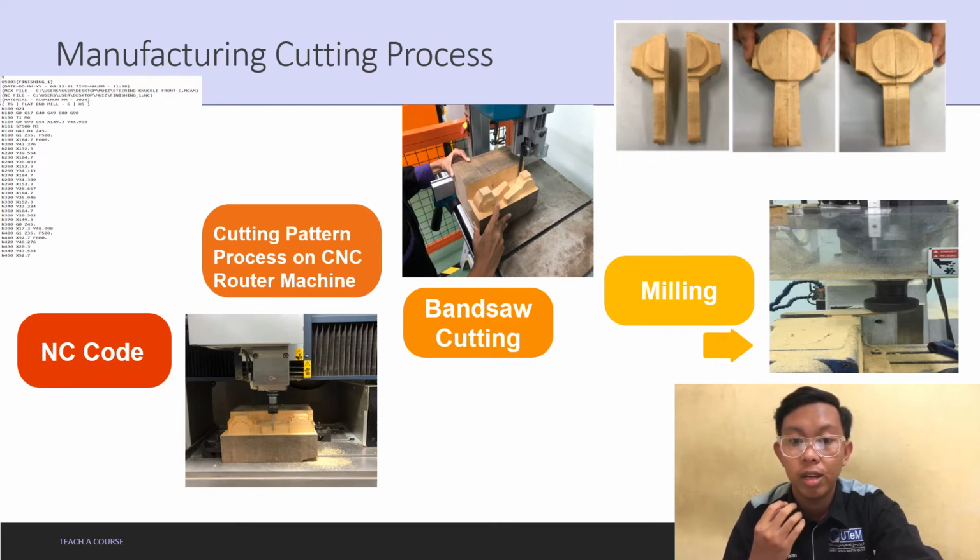As I mentioned on the last slide, all the part operation processes have been set up with the end mill D6 and ball mill D4. The types of cutting machining process have been selected: roughing, facing, profile contouring, and isoparametric machining.